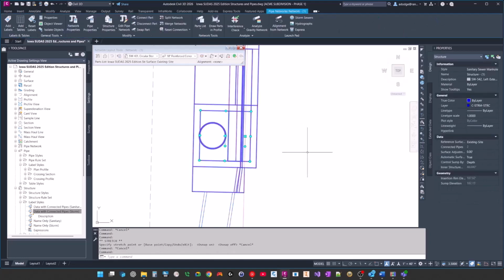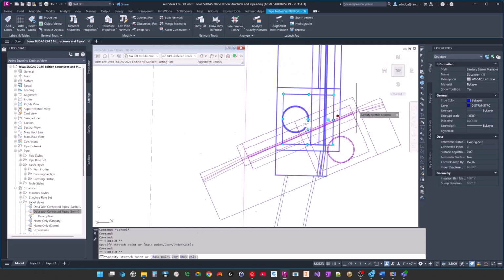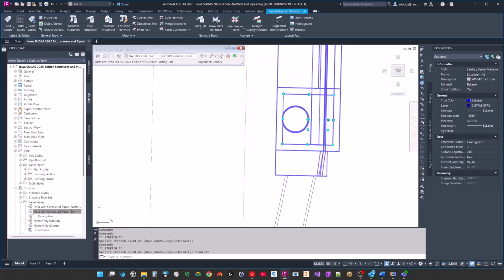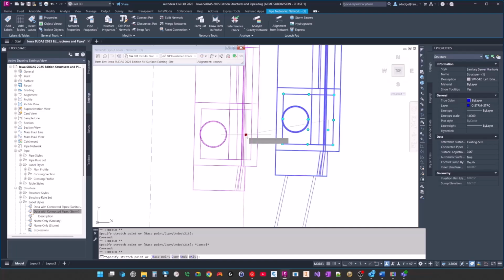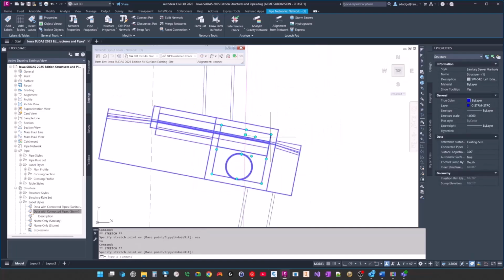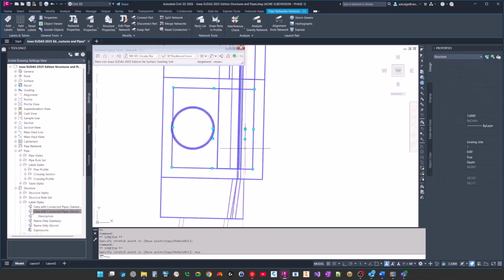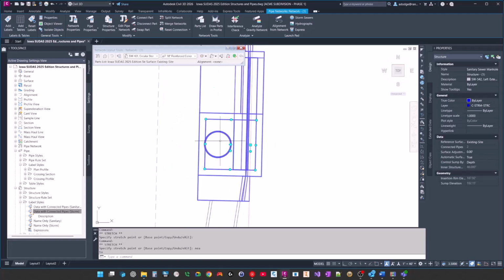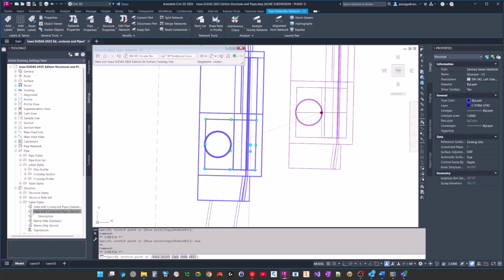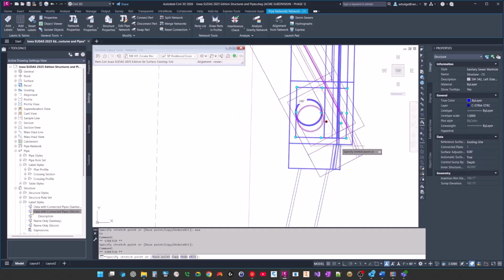All right, but in the case of the grips here, as you can see, we have the insertion point here at the back of the curb. It's going to allow me to move it from there, and we also have a rotation point there as well. So as you lay this out and apply this to the back of curb line, you now have the ability to rotate that so that it is in line with that back of curb. You also have the added ability here to move it based off the center of the structure and again rotate it about that location as well.